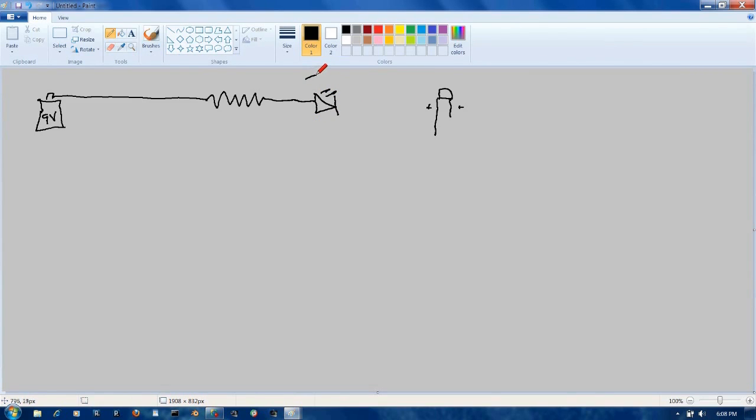That should actually look something like this. Depending on the schematics, I've actually seen it where people have drawn it like lightning coming off of these. But this is the symbol I see the most. They should have these little corners coming off for a light emitting diode. And then we go back to ground. So this is our positive, this is our negative, this is our positive, and this is our negative. Resistors aren't polarized. It makes no difference which way you put it in. LEDs are. So this would be the positive side, and this would be the negative side. So this is how we would put it in our circuit.